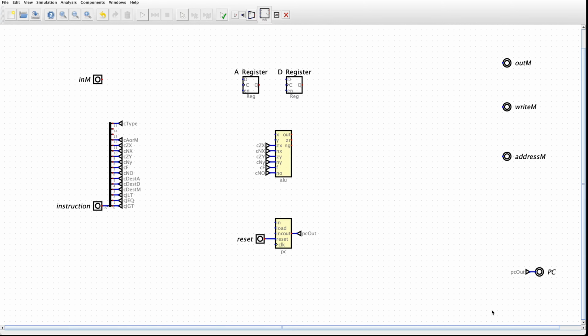Our jump logic is going to go here because what jumping is going to do is change the program counter. It's going to change it from being just +1 to whatever we decide it should be. And then we have our core CPU logic over here. So right now, as we look at what needs to be done, the thing that really jumps out to me are these registers. These registers are central to the operation of the CPU, but they're not connected to anything. And right now, there's not a lot of indications as to what they should be connected to.